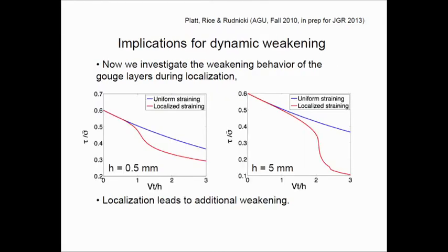Now, other things you see is that when this instability develops, especially in wider zones, if you deform this wider zone uniformly you would have the exponential weakening. But as we've seen, that's an unstable solution, and what the nonlinear analysis picks out is this really incredibly dramatic weakening that sets in once the average shear strain in the zone is somewhat above 2.